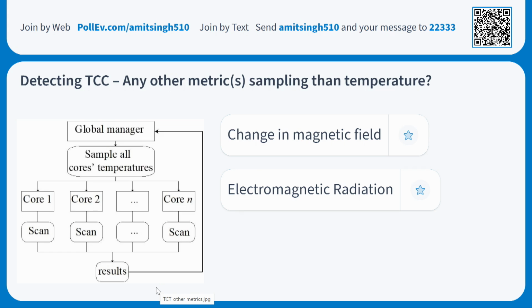There could be lots of other things you may potentially use. You can also look at the utilization of each core over the time, maybe 90%, 100%, 80%, something like that. Now if you transform that to the frequency domain, you might find that at a certain frequency there is high amplitude, which means there was a point in the processor where something drastically happened, the temperature increased, and then you can basically detect it.